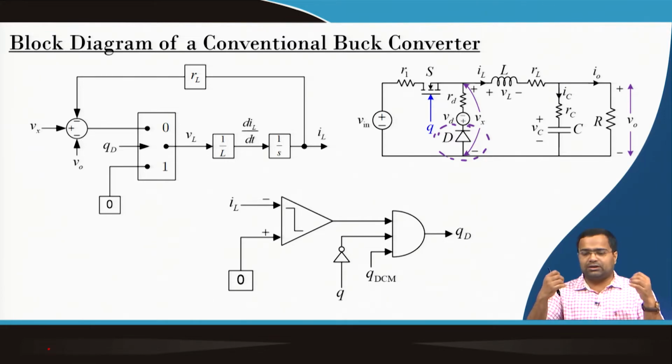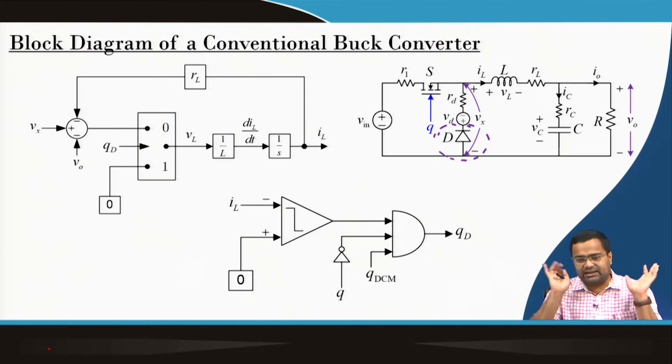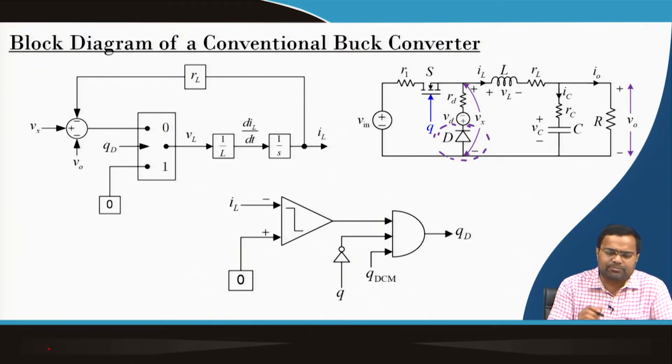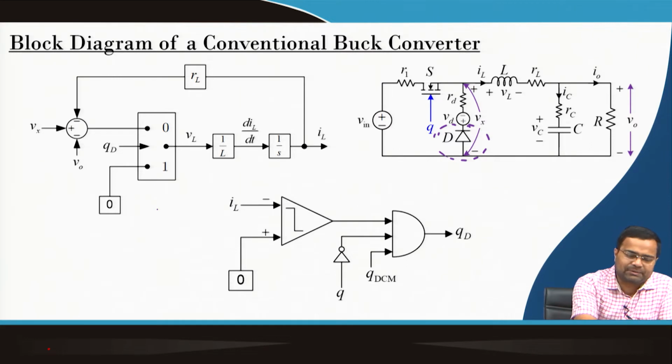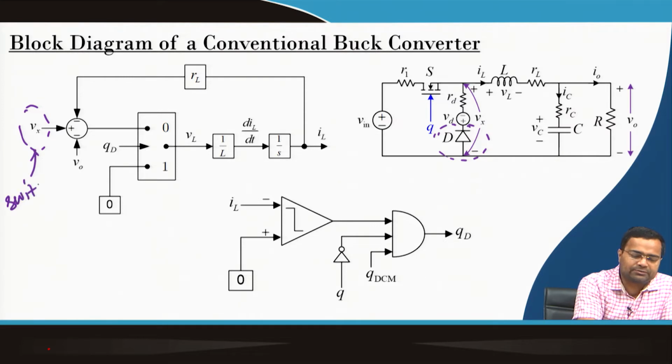We also want to show a comparative study by considering a load step down transient: what happens if we use a synchronous buck converter throughout, and if we enable a conventional diode buck converter. This model is well known, and we know that this particular signal is our switch node point, the switch node voltage.